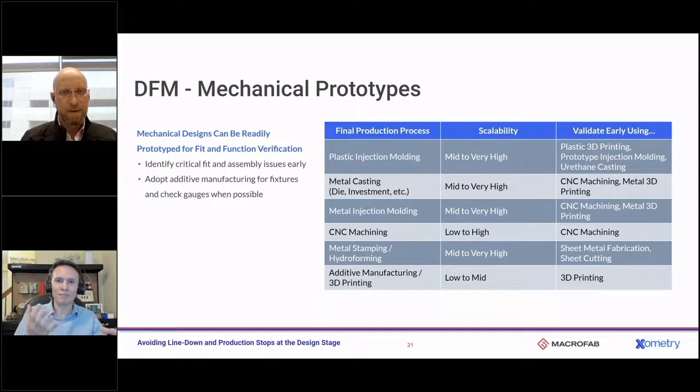But there's the techniques we use, even when I'm moving from CNC prototype to CNC production, may be different, but at least you can validate those results in very low volumes, and it's really good for those critical fit checks, for checking for assembly issues. You already have your jigs and fixtures ready, like they're available. We were talking before, you could actually prototype your whole bill of materials and just check the movements around. So there are techniques to get physical goods well before you're even invested in the hard cut steel tool, for example.